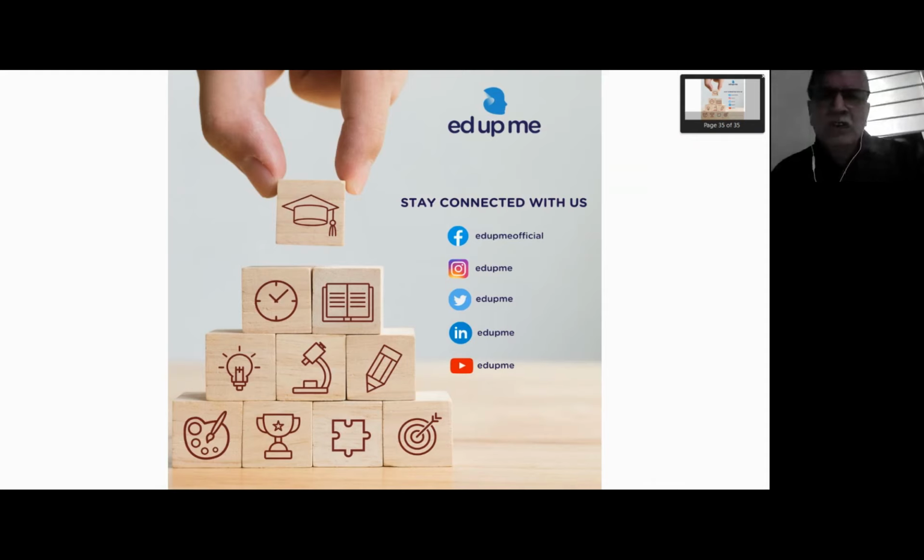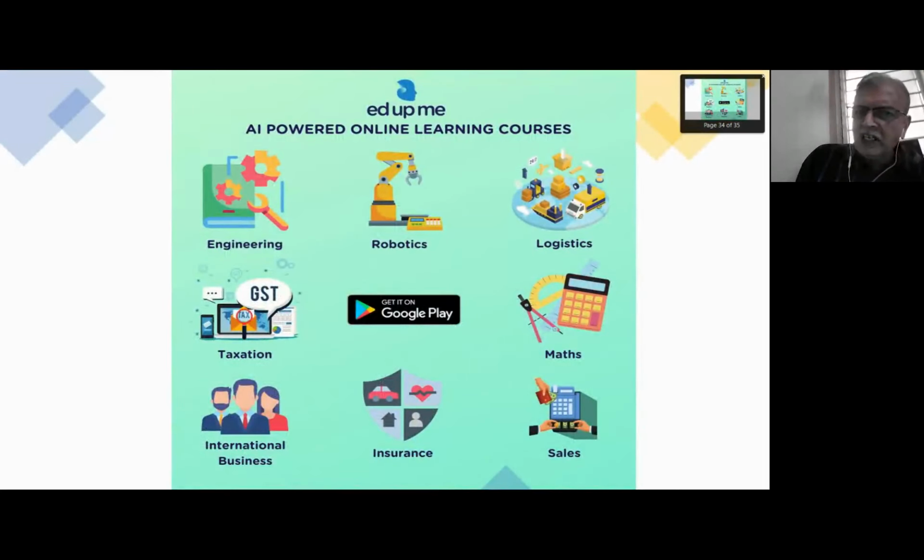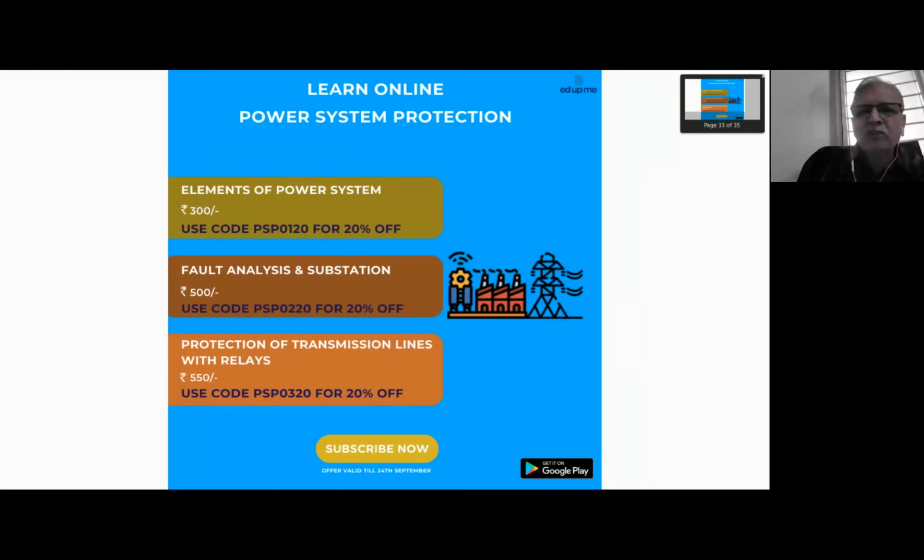Reverse blocking principle is actually, if there is a relay, one relay R1 is backing up R2. So once R2 senses the fault, it will give a blocking signal to the backup relay towards the source. If 2 transformers are in parallel, then there will be 2 backup relays, one R2 and 2 R1, right? So you have to give reverse interlock to 2 relays.